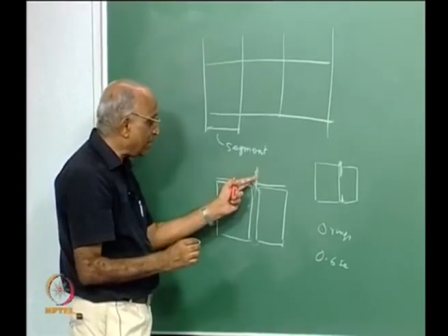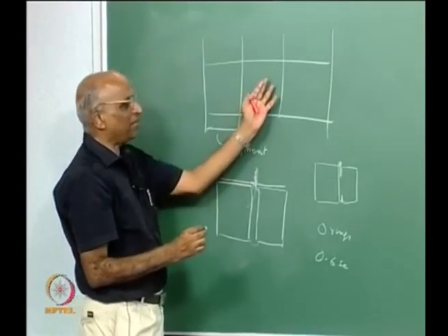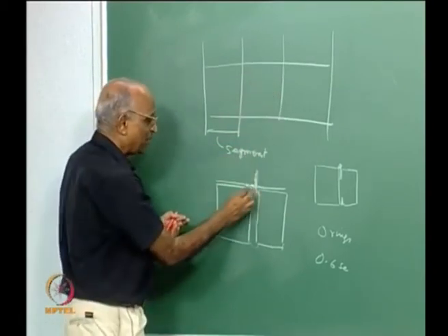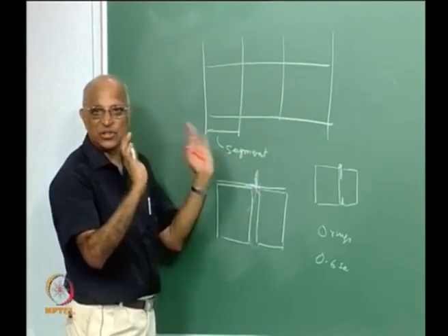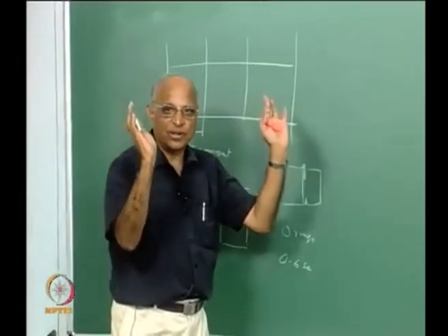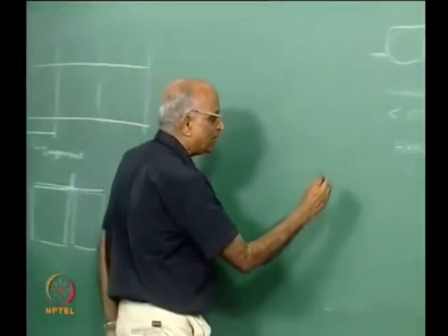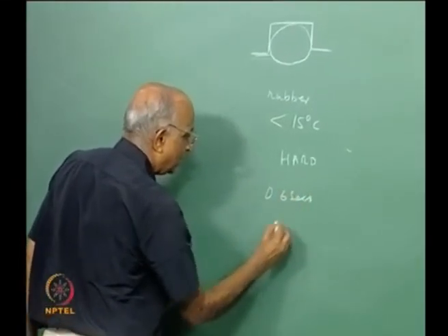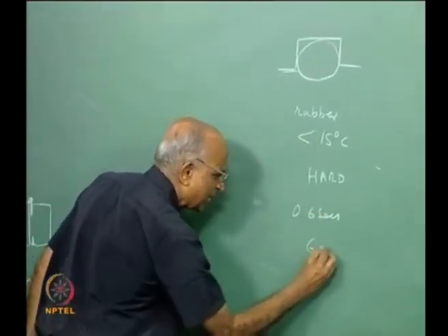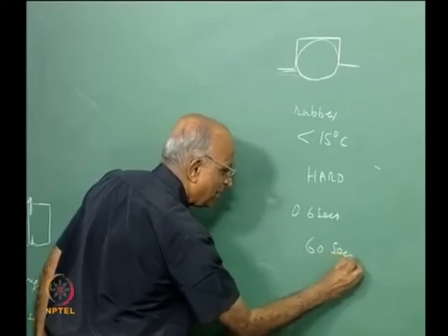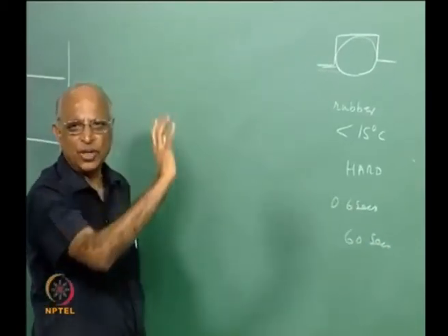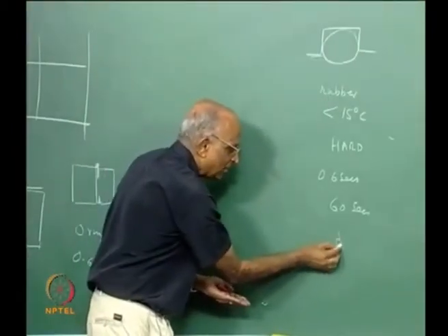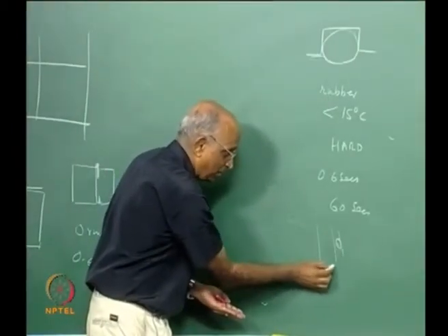These gases are escaping, but our propellant is highly aluminum. Therefore what does aluminum oxide do? It goes and blocks it. Well, the motor is still safe, it keeps on going further and further. From 0.6 seconds at which the O-rings have failed, up to something like 60, 62 seconds, the flight was perfect. It keeps on going because there is a hole, aluminum oxide blocks it, the chamber continues